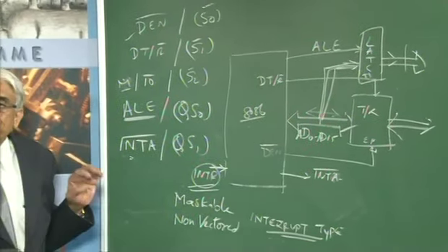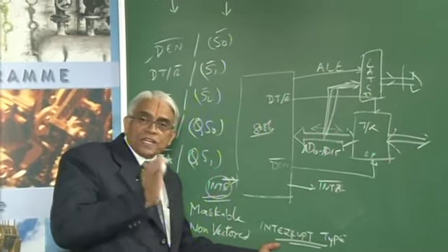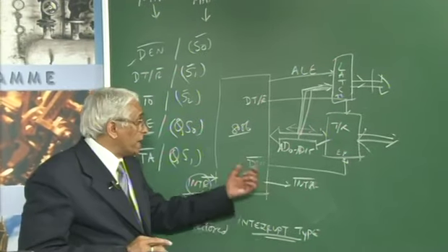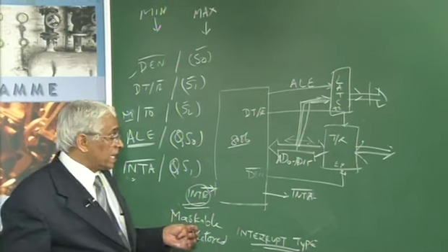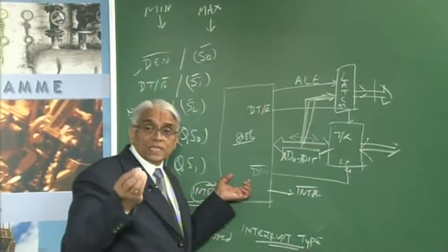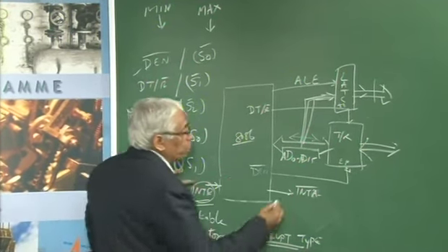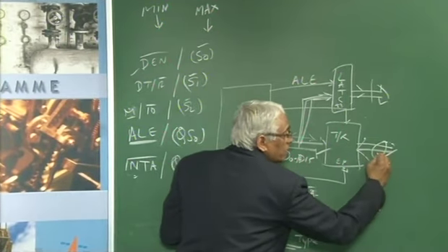There are 256 interrupt types. One of the interrupt type numbers has to be provided to the 8086. During the second interrupt acknowledge machine cycle, the interrupting device has to place the interrupt type on the data bus.